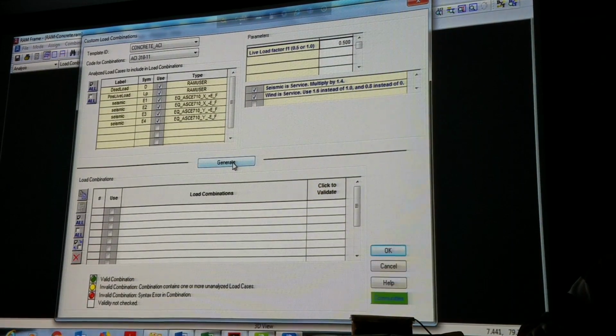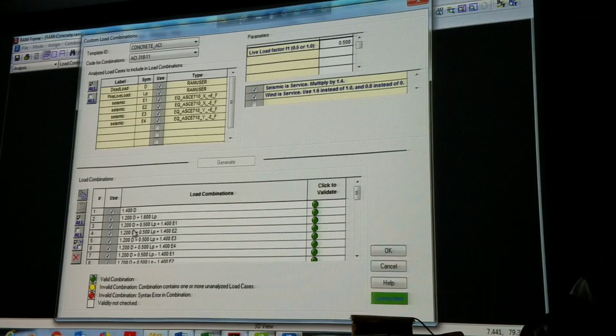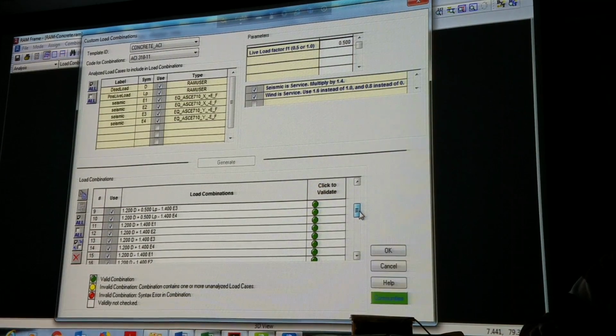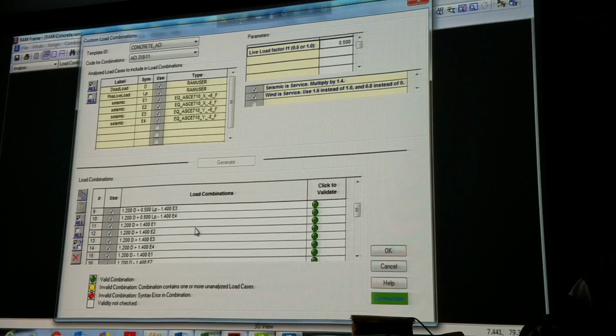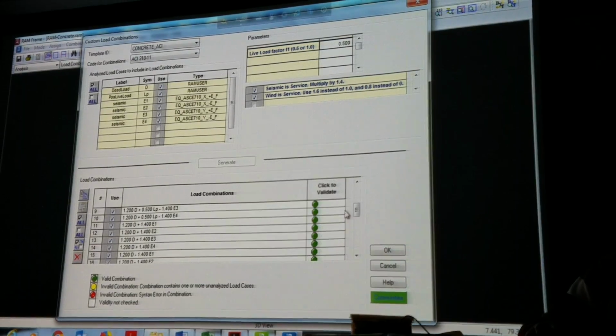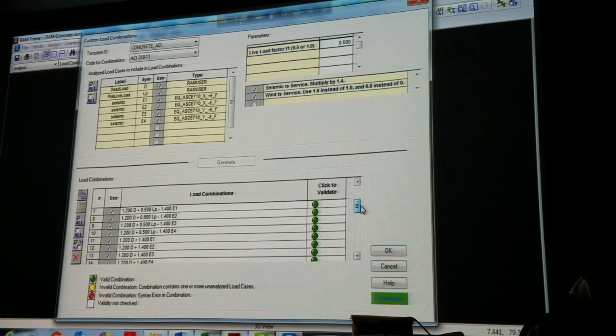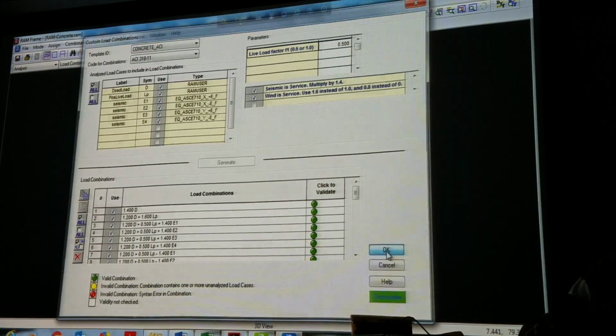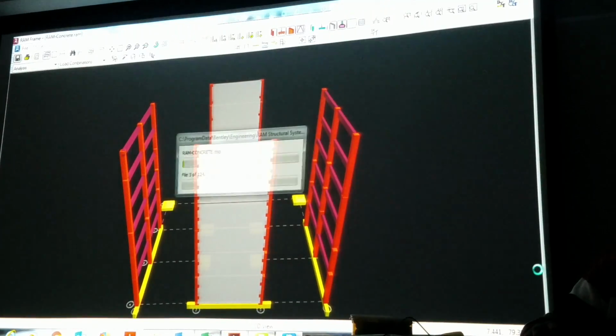So, I'm going to generate, and if you look into that, it's 1.2, 1.5, all the load combinations that we learned are actually here. Okay? So, one thing interesting is 1.2 dead load and 1.4 earthquake load. Why is there no live load? Because, I mean, it will be statistically too much. So that's the core load combination we are going to use, and I'm going to save it.